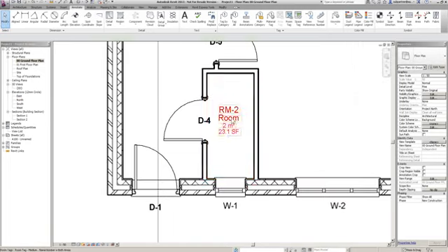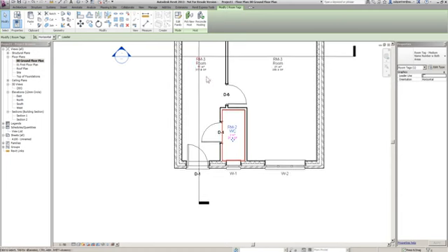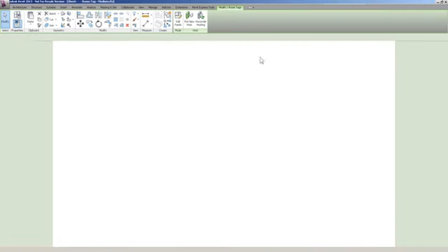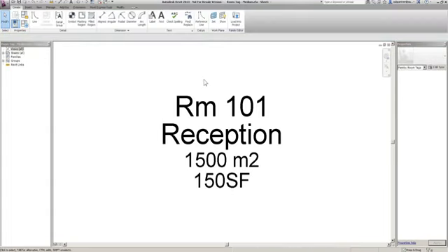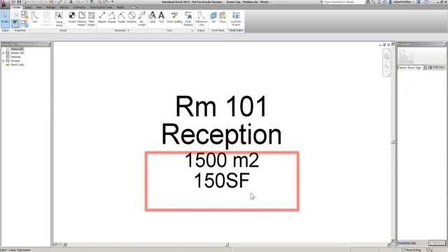I'm just going to rename these rooms. Okay, so that's going to be my WC. This one here is going to be my hall. This one here. What I've done there, this is a common thing that people do in Revit 2013. They've basically brought in a double click onto any family to edit it. I did it by accident there, but while I'm doing it, I might as well show you this very quickly.